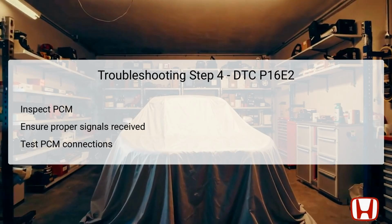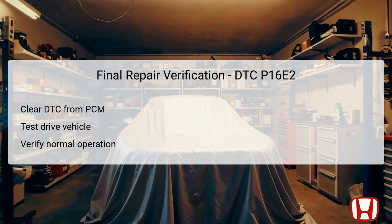Evaluating the PCM ensures that the core processor is functioning correctly, thus eliminating it as a potential cause of communication failure. After addressing the identified issues that led to the DTC P16E2, it's essential to carry out a final repair verification. First, technicians should clear the DTC from the Powertrain Control Module, PCM, to eliminate past errors and prepare for new tests.